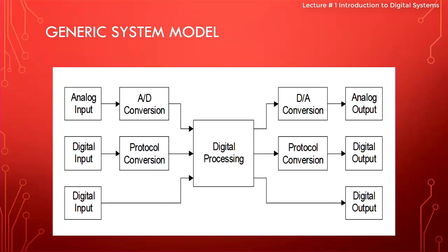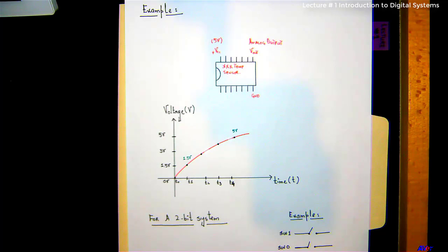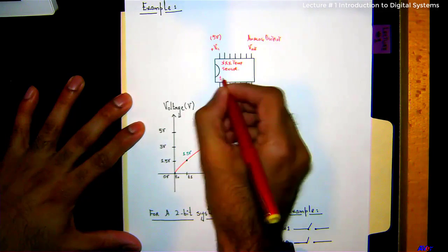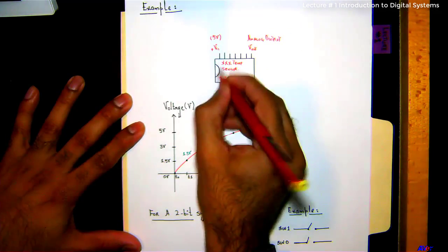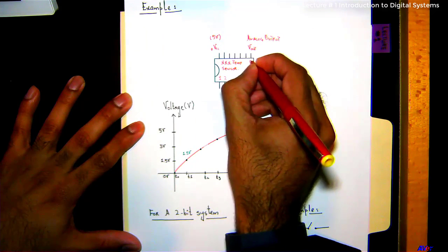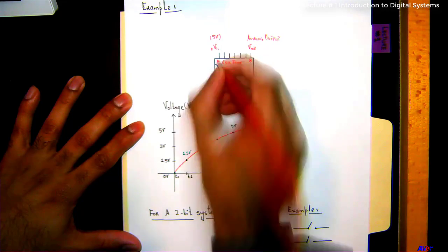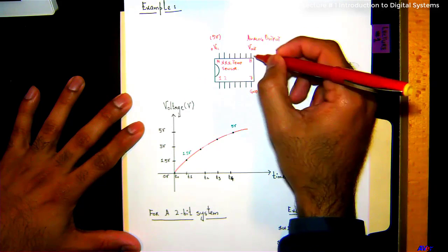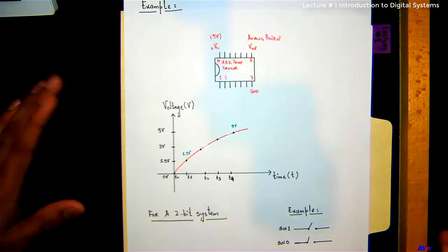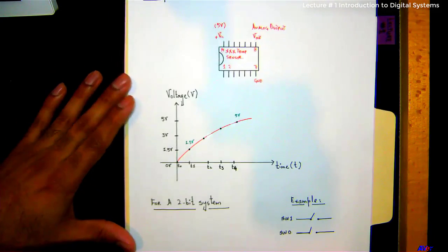I wanted to show you one more thing right here. Okay, say there is another temperature sensor, and it's a 16-pin sensor. So this is pin 1, 2. Usually when you see a notch, this is where pin 1 is. 7 is connected to the ground, 8 and 14. Okay, and this is your analog output right here, pin number 8. And this is just some sensor. I'm just making it up for the sake of the explanation.